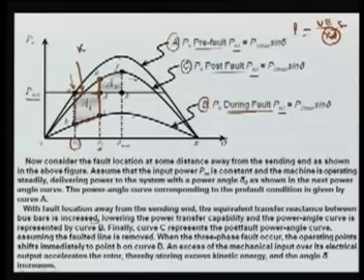When the three-phase fault occurs, the operating point shifts immediately to point B on curve B. Here this is coming here during the fault, and the excess of mechanical input power of this machine accelerates the rotor, thereby storing the kinetic energy, and the angle is increased here up to this point. So this is your point of movement. Here it is going back, and then finally it will be attaining now.